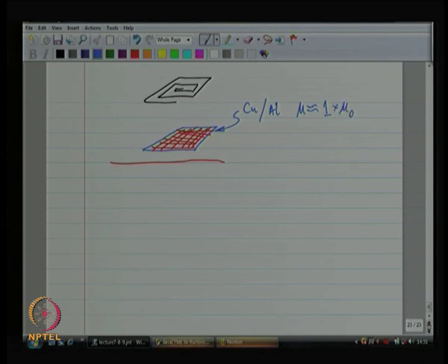Relative permeability 1 is the permeability of vacuum. Only materials that are far off from this relative permeability of 1 are iron, cobalt and nickel. So, as long as you are not using any of these 3 materials, iron, cobalt, nickel, you are in the range of 1. So, copper is probably a little bit diamagnetic, I am not sure. So, anyway, it does not matter.